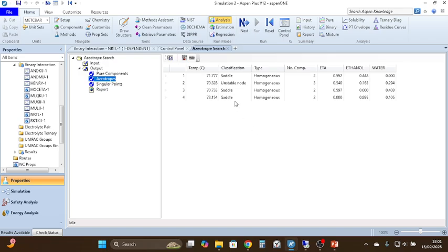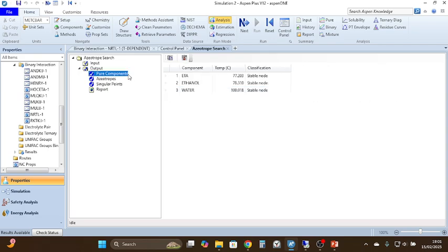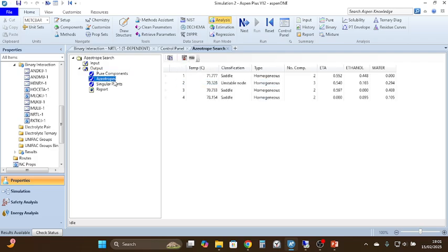So whenever we are trying to go towards this point of azeotrope, the point is going to move towards this temperature of 78. Okay, but that doesn't mean that we are going to get an efficient separation out of this process. And they usually take place in ternary mixtures only. In binary conditions, we hardly see any saddle azeotropes forming. Okay, so this is what it is.